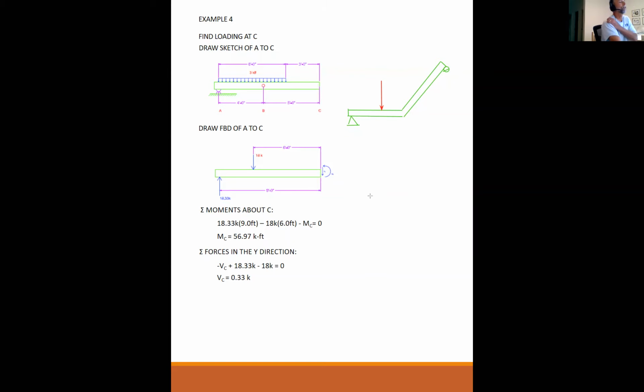That's a great question. This beam was simply supported, and the reaction at A in the horizontal was equal to 0. So I neglected to solve for N in all cases because N is trivial. It's equal to 0. But just recognize that if you had something like this, N will not be equal to 0, and you'll have to solve for it. Did that answer your question? Yeah, perfect. Thank you very much. Okay, thank you.